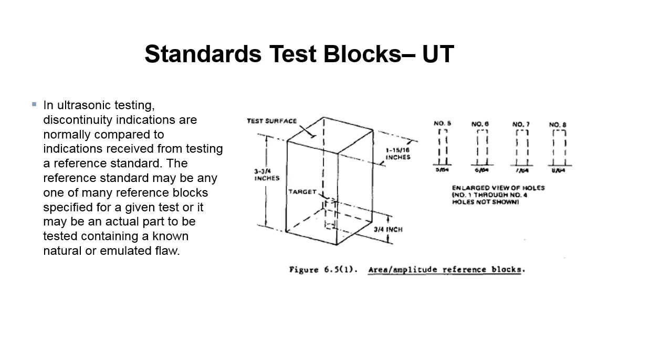So if he's doing an ultrasonic test on a certain type of carbon steel, then he's going to go get a standard test block for that particular type of material, and then he's going to calibrate his machine to make sure he can find a flaw of a certain size and depth at a certain distance, and then he's going to know his machine's calibrated. He's good to go. But if he changes from carbon steel to aluminum or another material, then he's got to use a different test block with another